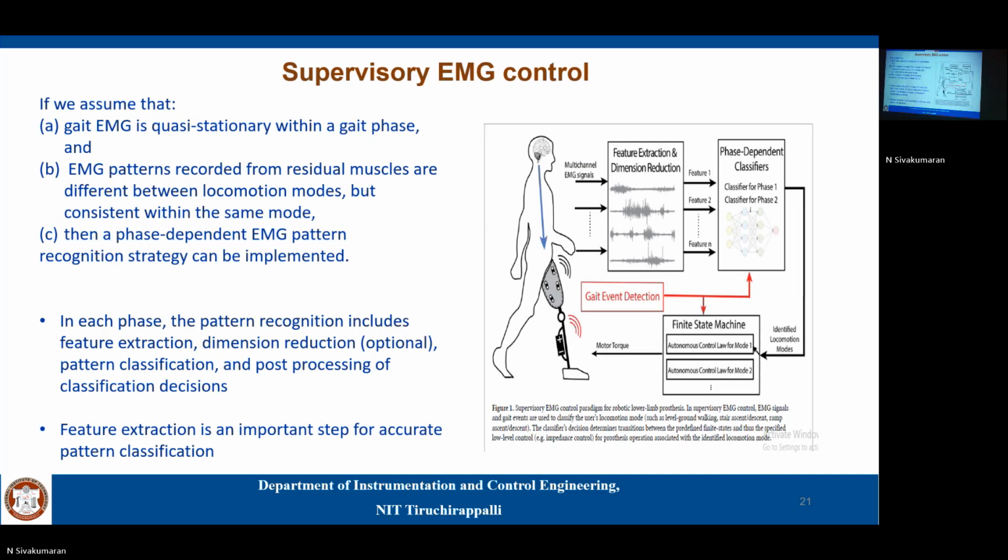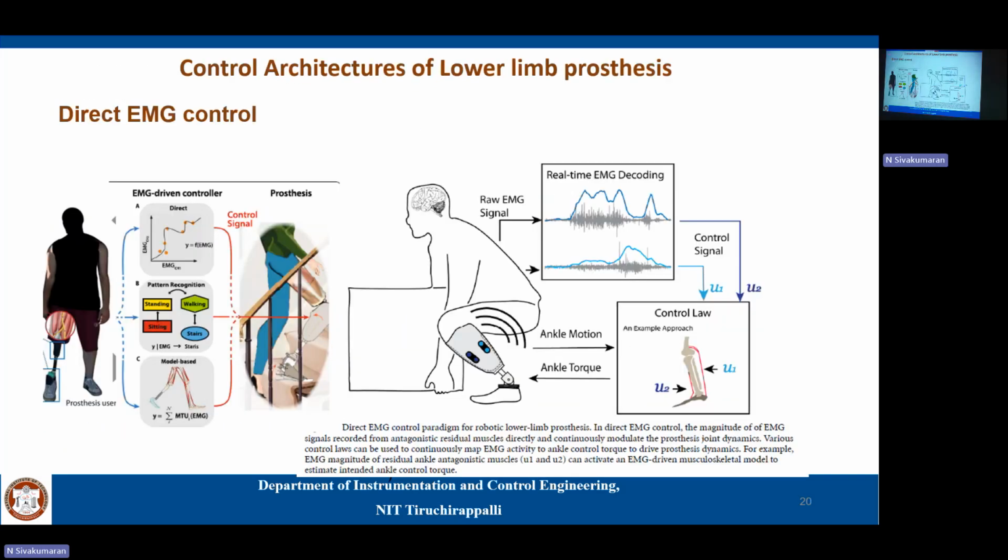Direct EMG means we collect EMG and do not do much processing. We just take the amplitude, or RMS or energy of the signal, to actuate the knee. That's it, which means we will not get a smooth movement, just an on and off kind of activity.